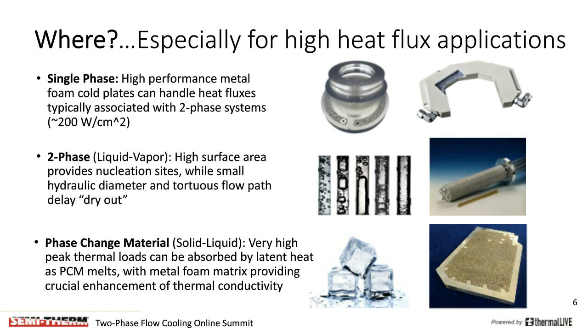Metal foam also performs extremely well in solid liquid two-phase systems, typically referred to as phase change material or PCM heat exchangers. Here, peak thermal loads are absorbed into latent heat as the PCM melts, while a metal foam matrix provides crucial enhancement of thermal conductivity, allowing very uniform temperature profiles throughout the melting process.